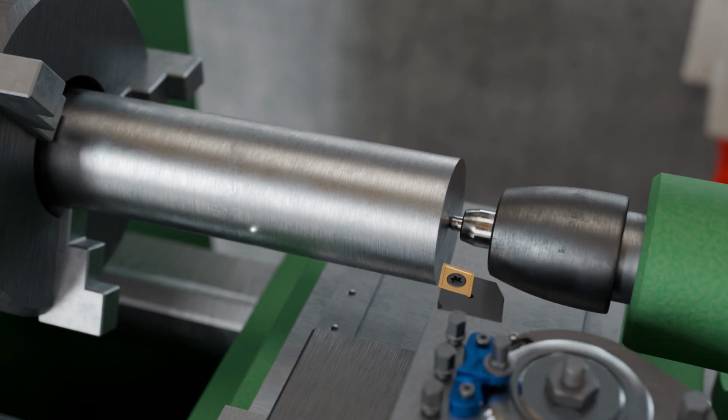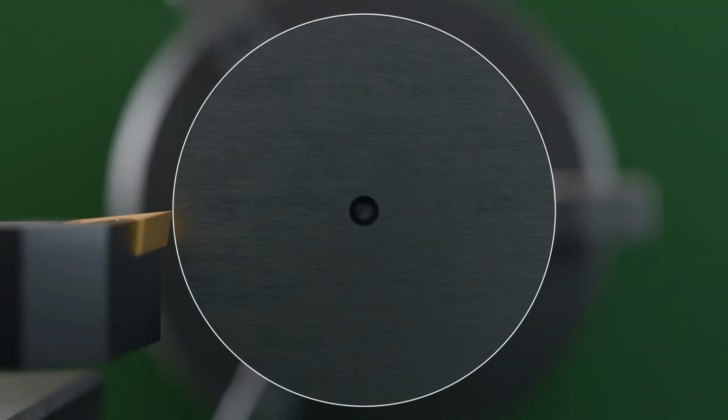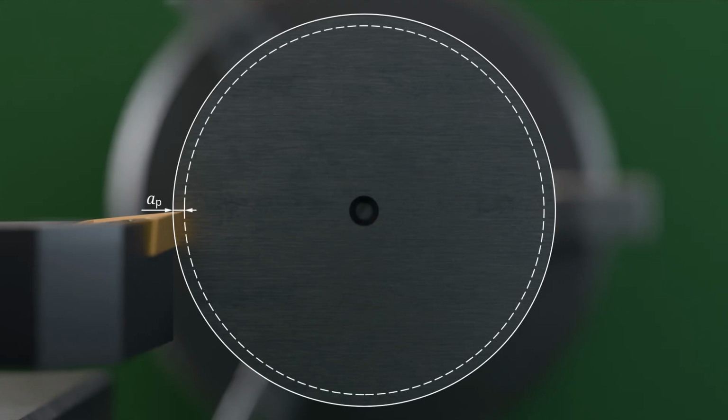Depending on the generated surface and the feed direction, that is, whether turning is performed transverse or longitudinal to the axis of rotation of the workpiece, different turning processes are distinguished. To produce a specific diameter on a turned part, the so-called longitudinal turning is applied. In this process, the infeed at the beginning of the turning operation is made in the radial direction. The depth of cut, AP, corresponds to the reduction of the radius.